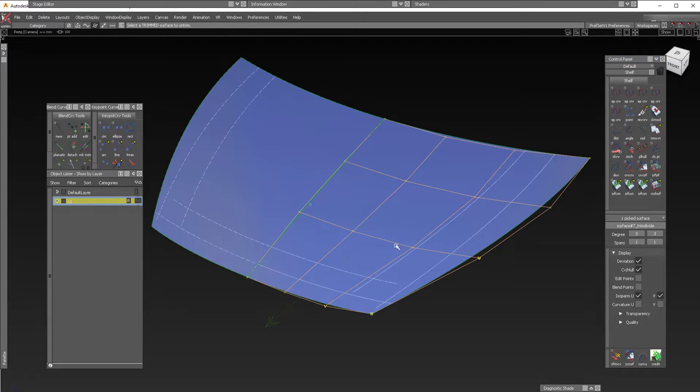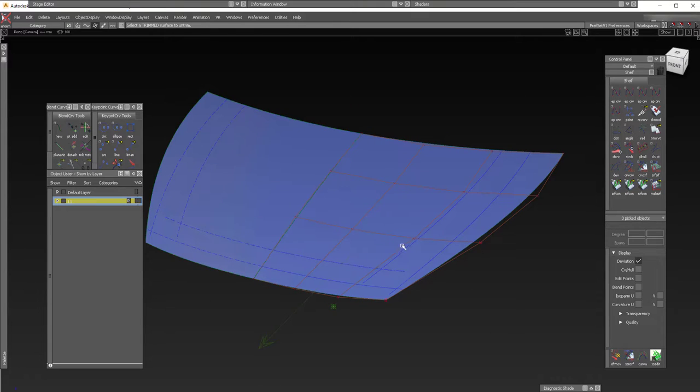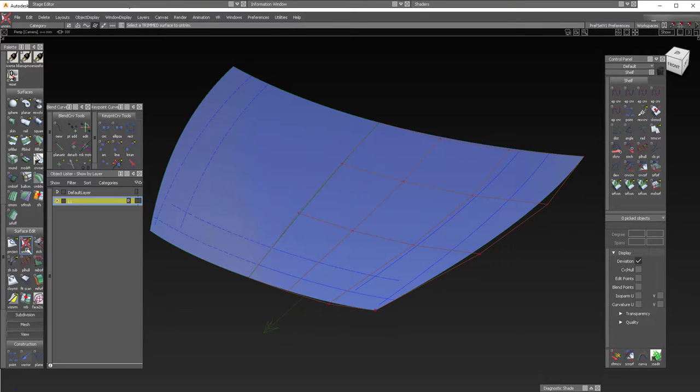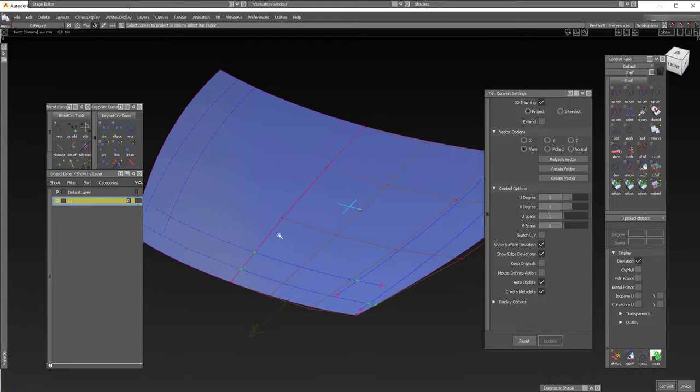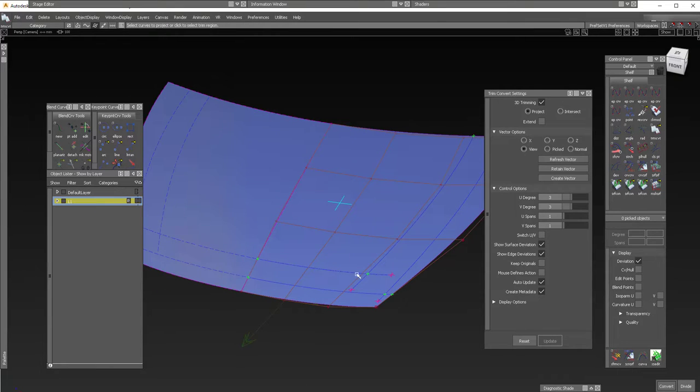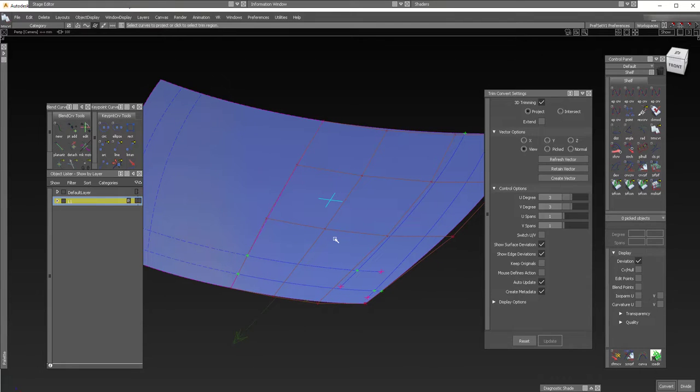Let's untrim this surface that we divided like 2 seconds ago, and there is a tool for that, which is the trim convert tool. Right next to the untrim tool here there is trim convert. Selecting it and clicking once, the area that needs to be converted, it works like this. You have to have 4 boundaries. In this case, this curve on surface is the first boundary, the other curve on surface the second boundary, the third and the fourth. Not less than 4, not more than 4. Exactly 4. So I go like convert.